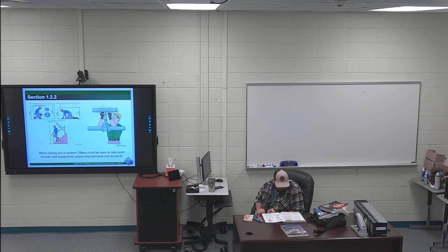Second paragraph, right after where you see the NEC, so I guess it might be the second sentence. Online test question. For example, a minimum headroom of 7 feet measured from the lowest point of the piping should be maintained in pedestrian areas. Obviously, you don't want to put a pipe at 5 feet that people are going to walk into if they're in a pedestrian area. It has to be a minimum of 7 feet in pedestrian areas.